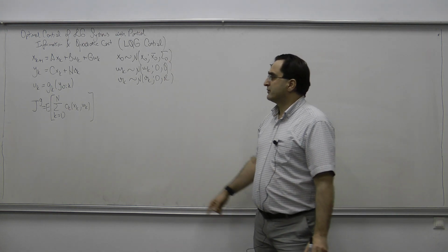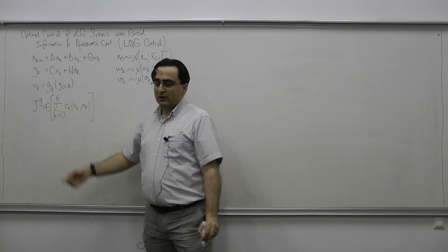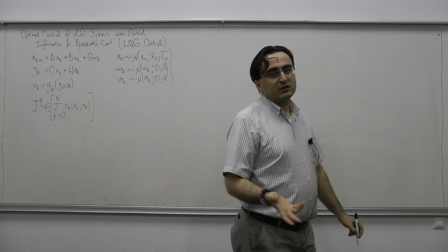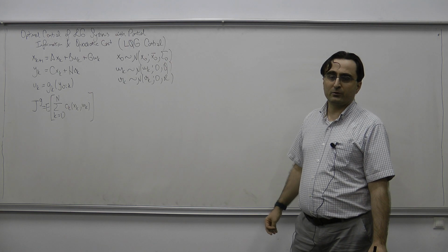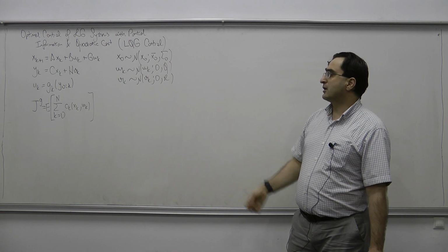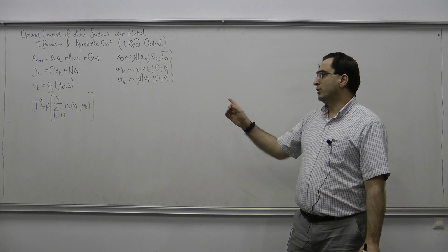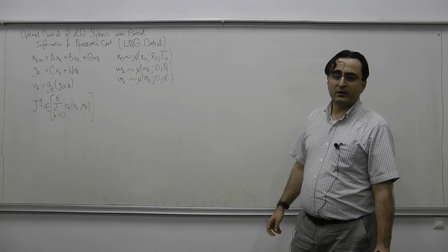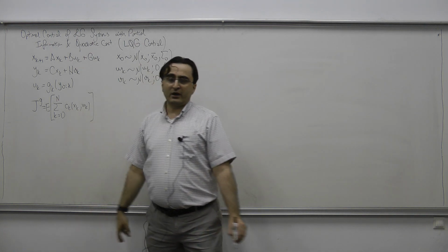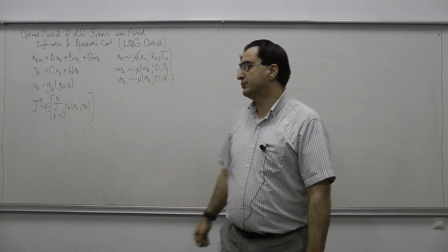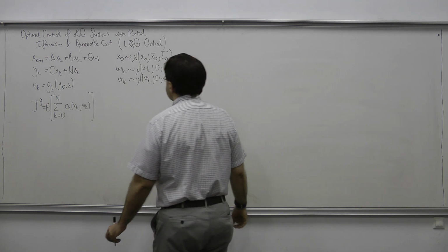These cost functions can be arbitrary in general, but with general cost functions, we don't have closed form solutions for the control, as in the case of the quadratic cost. So here we are going to be considering only the quadratic cost. But of course, in general, these cks are arbitrary functions of xk and uk.